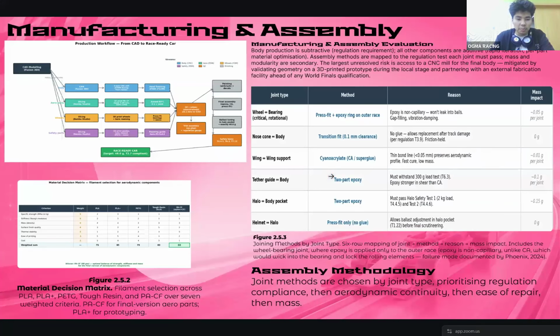For the printed parts, we keep infill low and use a gyroid pattern, which is strong in every direction, and we prototype in PLA before printing the final parts in carbon fiber. More you can see in our portfolio.